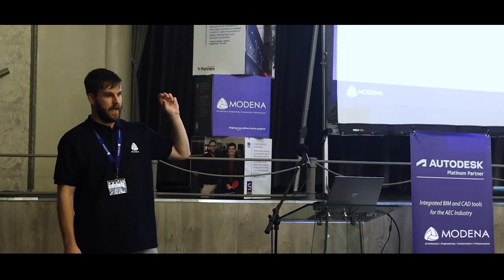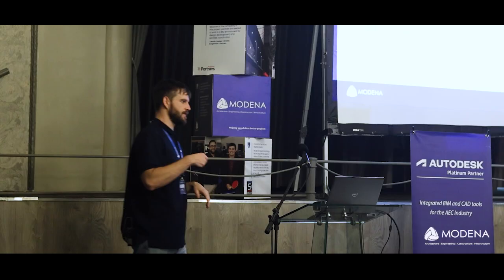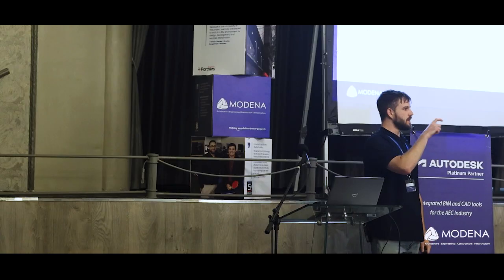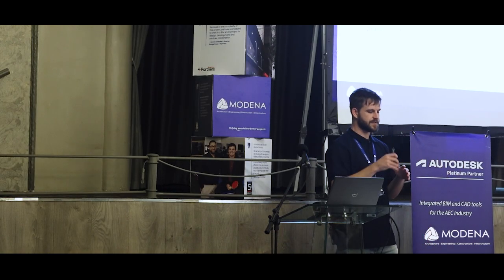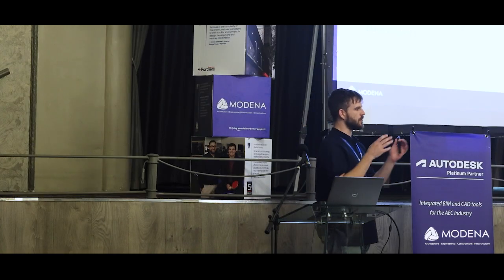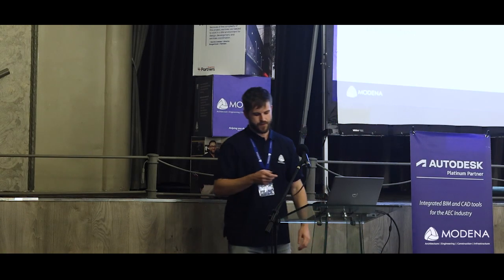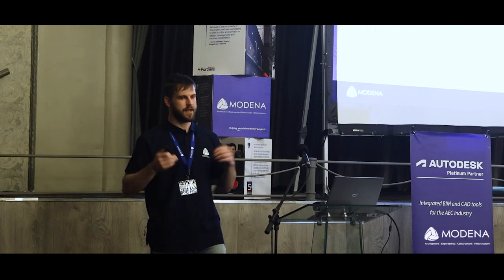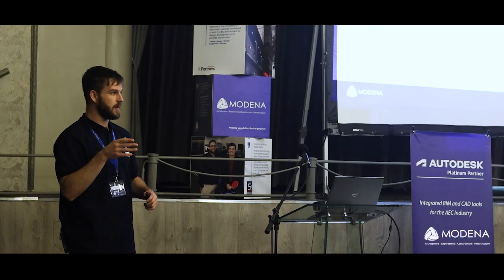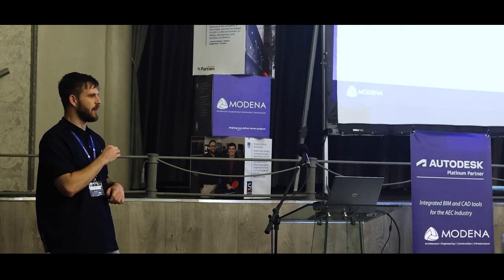With the workflow that I had at this stage, it was a factor of it does not put perfect models out. I have been able to refine that to make sure that when we load our elements into the grading optimizer, building your tools for your grade, your site limits and stuff like that, break that down into its own separate iterations that you are running. Do one element at a time, and then you will be able to get to your perfect tie-in elements. So once again, look at not populating too much information at once within the system. Understanding the system's hierarchy and taxonomy will allow us to highly refine the workflows to get the output that we require.